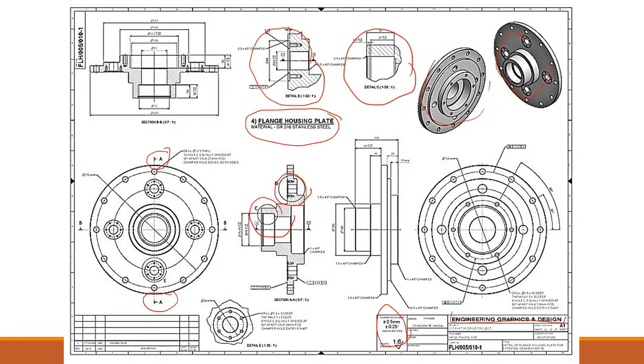So what you can see is that this sort of drawing is a full functioning drawing of all the things that we spoke of, or most of the things we spoke of, that shows how this works in the real world now. And knowing all of these, you can reference back and start figuring out how to make this component, how to communicate it, and if you have a part that isn't made properly, you can actually go back to your supplier and address any issues. You can also see, just based off of the tolerances, exactly what you're going to have to do to manufacture this component, as well as how you're going to have to clamp it or restrain it when you do any type of inspection. So that's some of the basics of engineering drawing and understanding an engineering drawing.